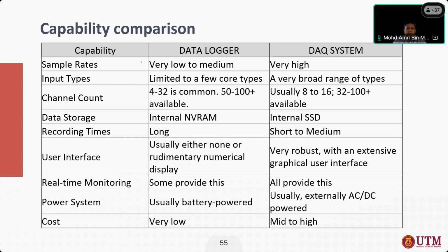For example, the sampling rate. Sampling rate means how fast the data can be sampled. This is very important when you know that the data you collect has a variation in frequency. If frequency matters, then you need to choose the proper sampling rate. According to the rule, the sampling frequency must be at least two times higher than the frequency of the signal.